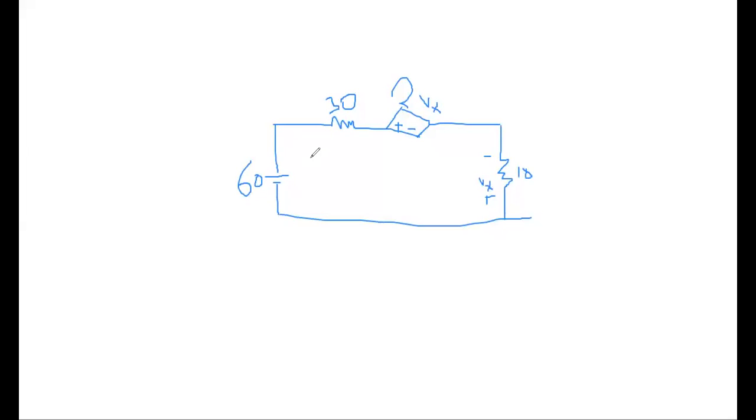Now all of you, what is the first step for any circuit? Okay, first step is nothing but assume the loop current in clockwise. Clockwise is the first direction. So we have to represent the loop current. We have to write let I be the loop current, and loop current is taken in clockwise. That statement is important. Now apply KVL. KVL says in simple language, write all the voltage sources to the left hand side. Now anyone tell me, is it plus 60 or minus 60?